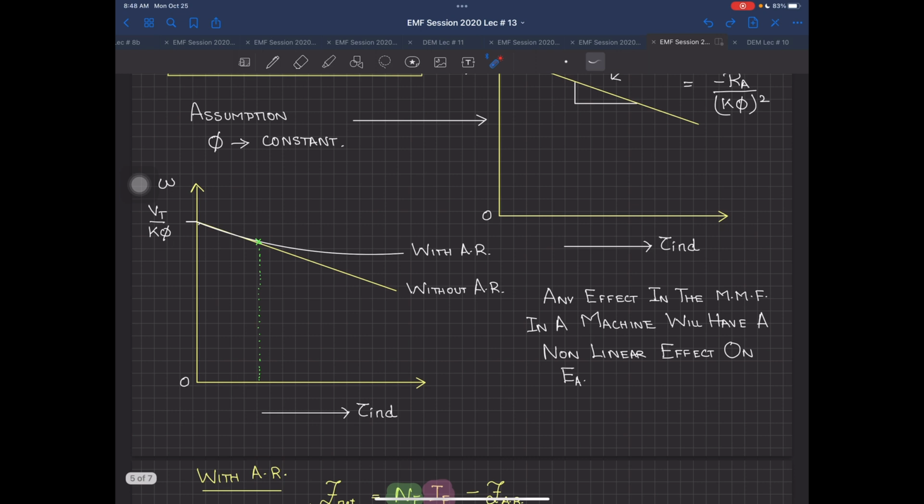Similarly, over here, this can be the full load point, where your full load torque is actually going to be produced. What is full load torque? Corresponding to full load torque, your full load torque is equal to K phi IA. And what is IA? This is the full load or rated current of your machine. So in your lab, you have your armature current rated at 3.5 ampere.